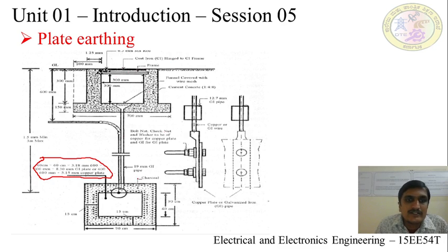For maintaining the earth resistance less than 5 ohms, you are going to pour the water periodically in the earth pit. This is plate earthing.